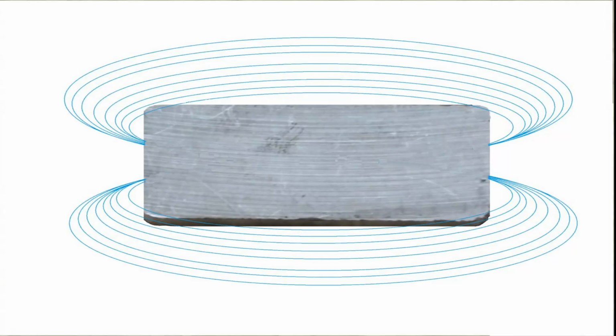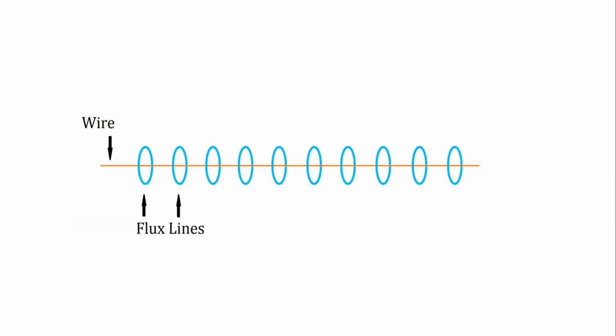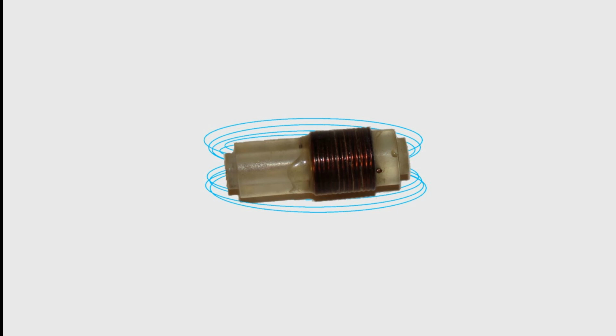Now, magnets, whether permanent, bar magnets, or electromagnets, have lines of force called flux lines that encircle the bar or rod and run through it. If you apply current to a straight wire, magnetic forces or flux lines will form around the wire, although they are not strong. If you wrap a wire to form a coil and apply electrical current, you have an inductor with a stronger magnetic field because the lines of force strengthen since the coils are aligned with each other.